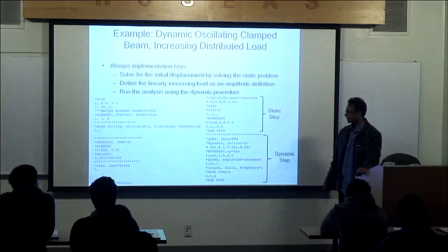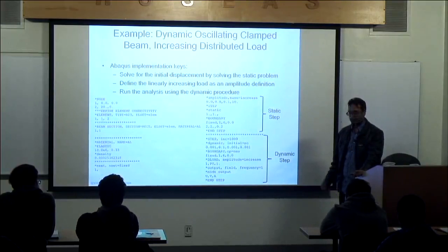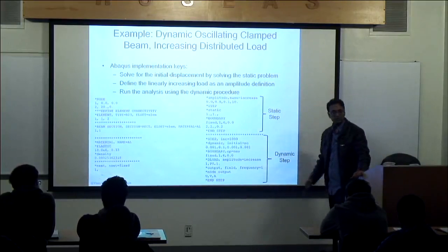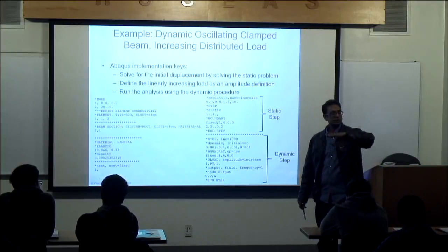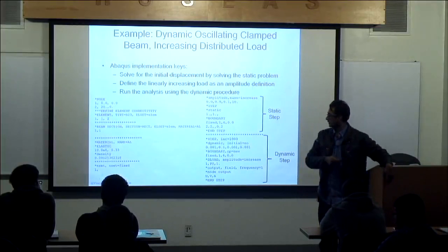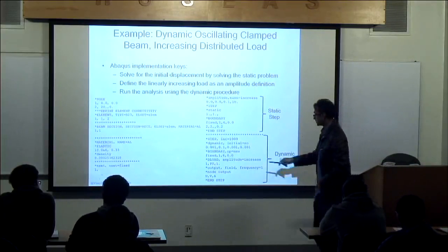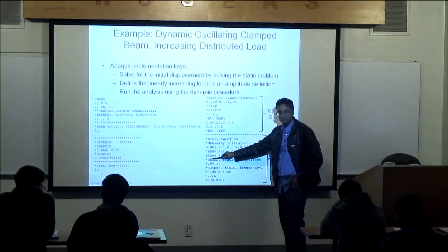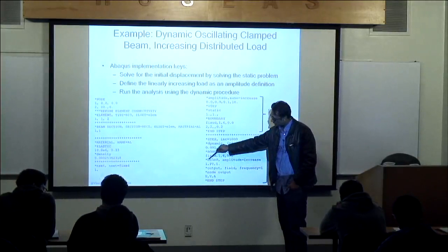Py is my Q, basically, the distributed load, the transverse distributed load. Py is what Abaqus tells you to name it. A distributed load in that direction is Py. And then Px is axial. You can look at the Abaqus manual, the keyword manual. That's what I go to. Star deload, and I look it up.